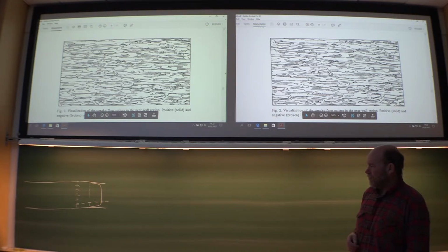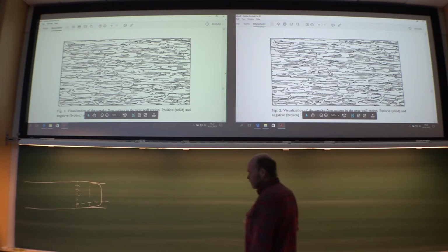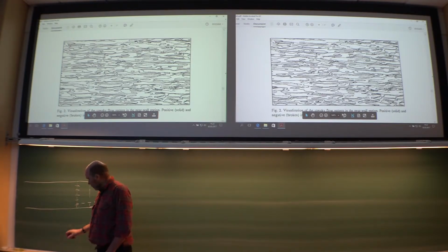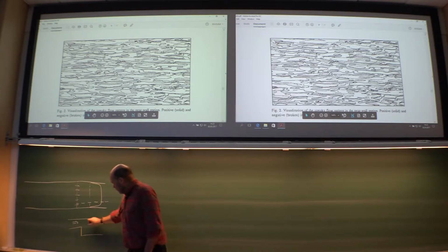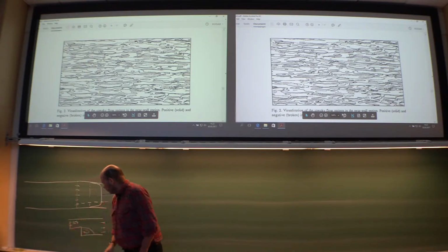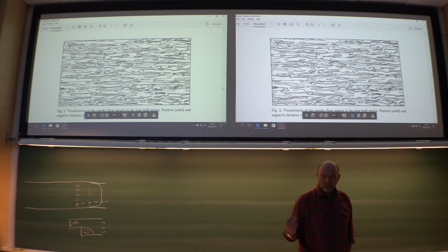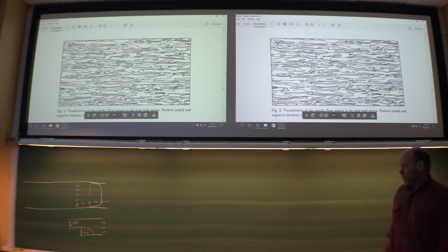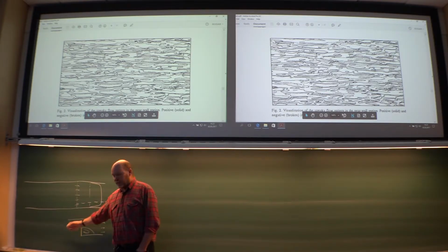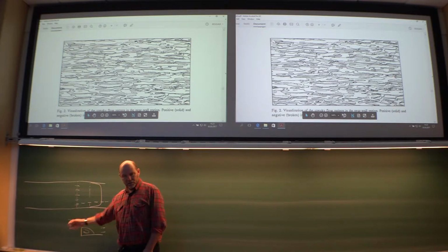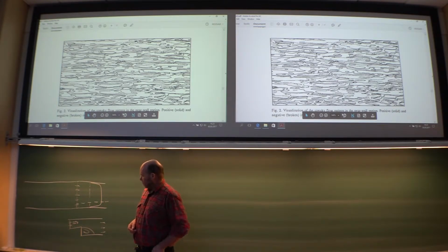Then you might argue, then this is pretty worthless, isn't it? If you have now, say, a more complex problem, something like flow over a backward-facing step, for instance. Now what? Well, you will have this zone here, of course, and then the outlet here, and then the inlet here. How can you simulate that one with the DNS? Well, you can't use periodic boundary conditions. You can't patch whatever goes out here and send it in again. There are two different simulations, two different solutions.